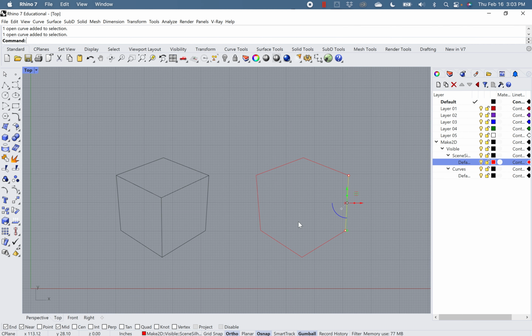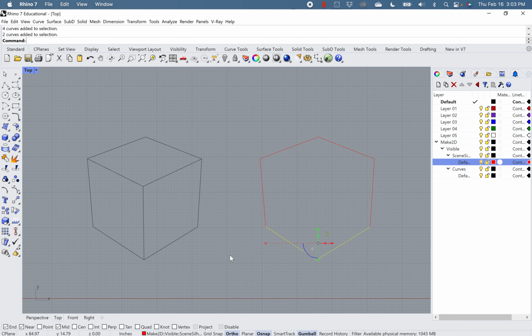So say as an example, you have a horizon, or if your drawing is sitting on a site, you can give the top lines that are above the horizon or above the site a different line weight quality than the lines that are below the horizon or below your site. And again, it's there to serve to give your drawing some depth. I'm going to turn this layer off.